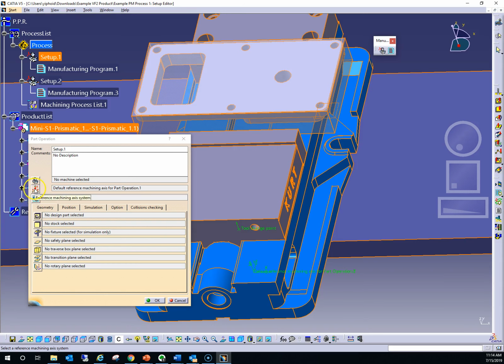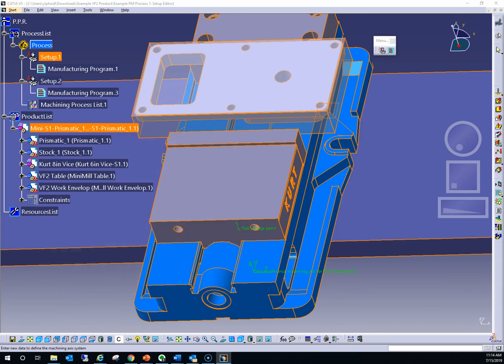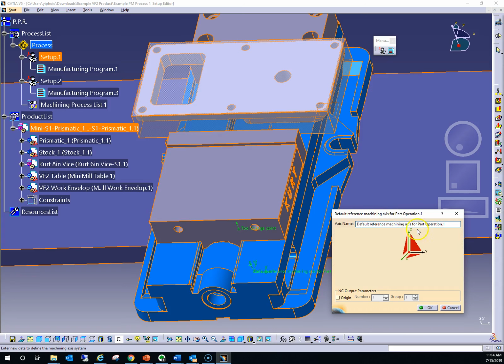So let's go ahead and click on this button, the second button down, and this dialog window here shows you a depiction of the coordinate system. Notice if you move your mouse over the red areas, they turn orange, and this indicates that they are pickable. The first thing that you should do, notice that there is a dot here which defines the origin of the coordinate system. There are also two arrows, one indicating the x-axis and one indicating the z-axis. So between these 3 or 4 pickable regions, one can position the coordinate system and orient it the way you want to.